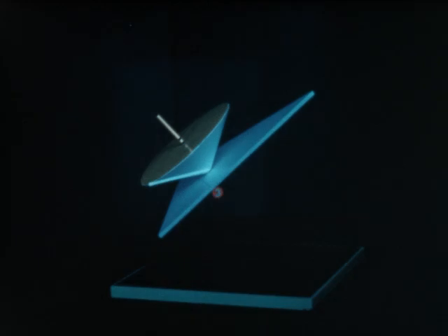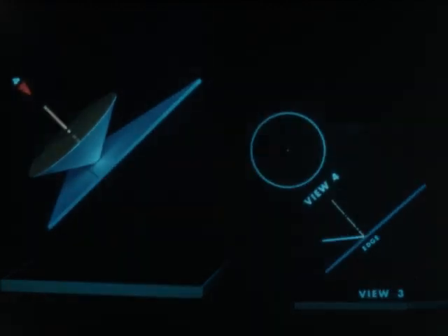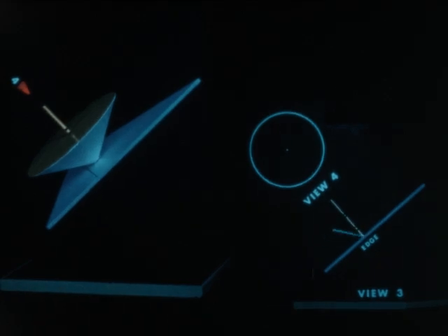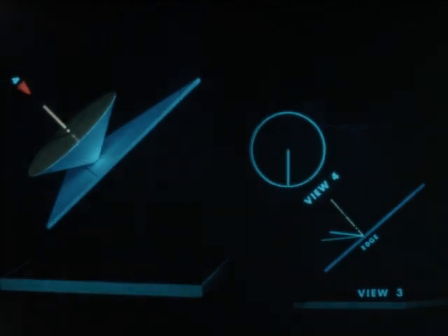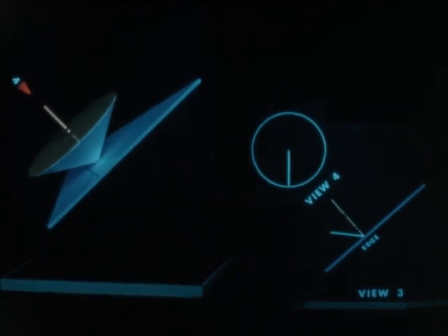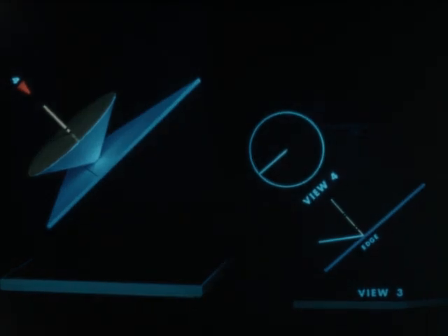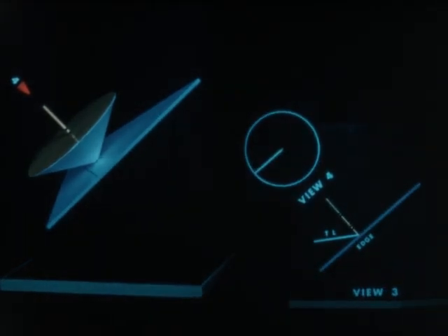A view 3 will show the plane as an edge and the right cone and plane relationship. View 4 shows the axis as a point and the position which the revolved line must take to show it in true length in view 3. Here the angle can be measured because the true length of the line and the edge view of the plane appear in the same view.